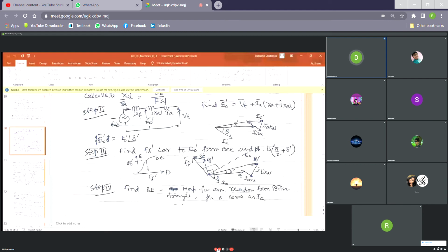পোর্টিয়ার ডায়াগ্রামে। এবারে দেখো এই যে Potier triangle-টা, তার significance-টা বললাম, D is the IAXL drop. But you see, if you consider this horizontal line BC, or rather BE, CE, etc., these are on the MMF axis because they are parallel to MMF, right? Now, out of which CE will represent the MMF corresponding to the leakage reactance, and BE will actually represent the MMF corresponding to armature reaction.